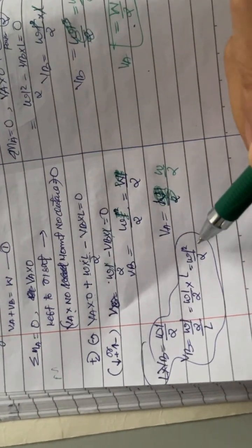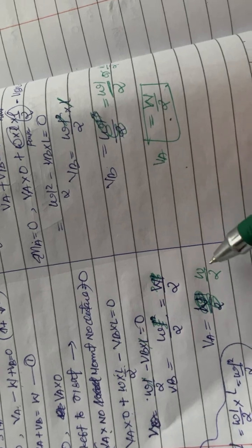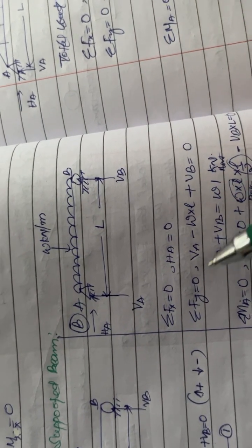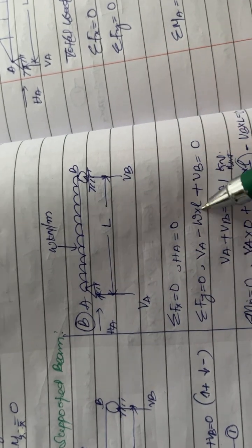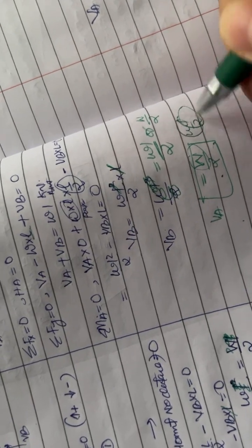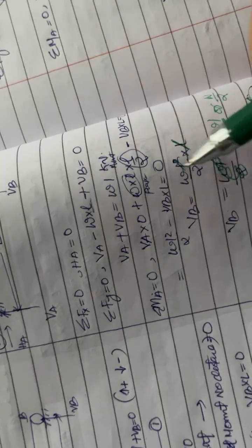तो जब आप इसको पूरा सॉल्व करेगा तो यहाँ से W/2 निकलेगा. यहाँ से आपका VB इक्वल्स टू W/2 निकलेगा और VA इक्वल्स टू W/2 निकलेगा. बस अगर आपका ये सिंपली सपोर्टेड बीम है तो आपको क्या करना है? बस यहाँ पे समेशन F of y में क्या करना है? ये UDL में तो इसको पॉइंट लोड में कन्वर्ट करने के लिए यू नीड टू मल्टीप्लाई विद लेंथ एंड VB. इसके बाद यहाँ से करने के बाद यहाँ से आपका आ जाएगा W/2. दिस W/2 इज माई WL/2. हाँ, आप ये W/2 मत सोचो, क्योंकि कैपिटल लेटर को हम WL भी लिख सकते हैं ना, उसी तरह से.